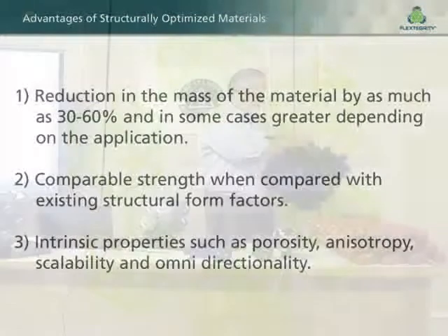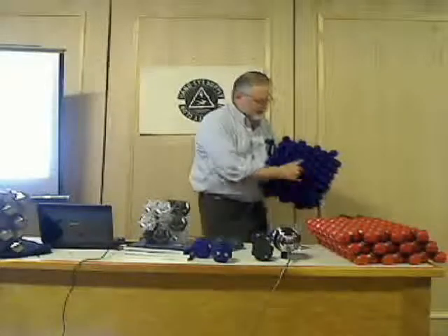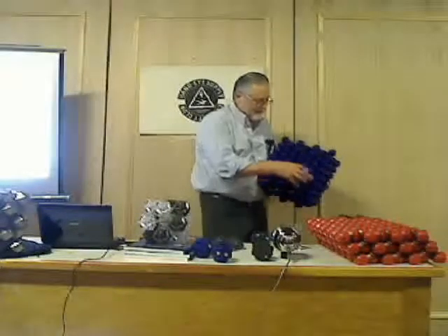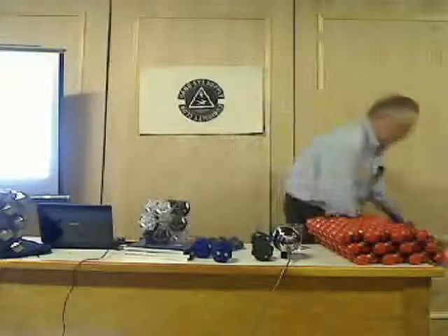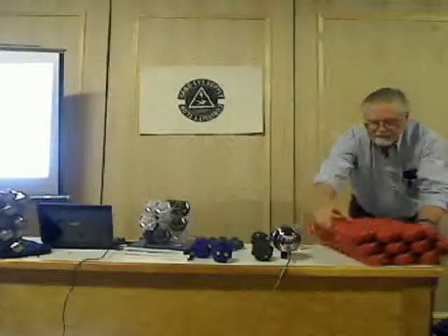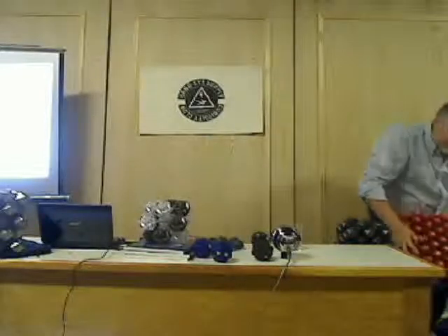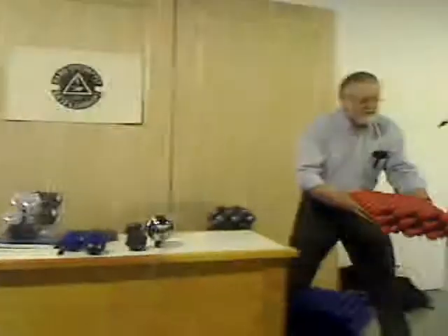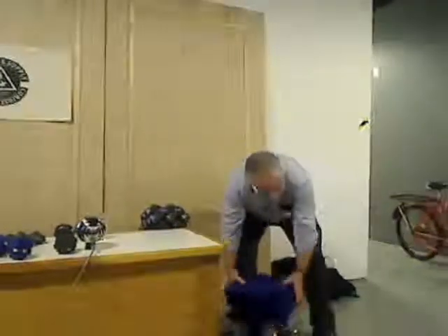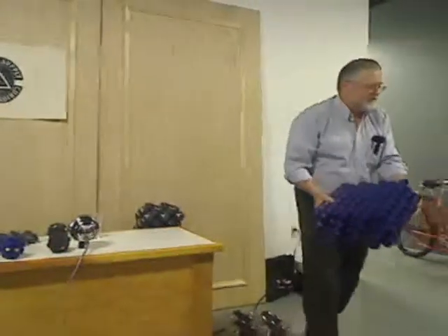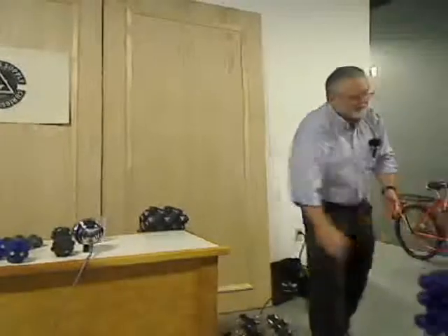And so we think of elasticity like this. So here's the same thing. I'll pass that around. There's the same thing. And all I've done there is change the interconnecting element. And that interconnecting element is acting in tension, and the icosahedron is acting in compression. And so we get a tremendous reduction in mass in the material, and it turns out that that's the sweet spot. That's where everybody wants to be. And that's strength over mass.